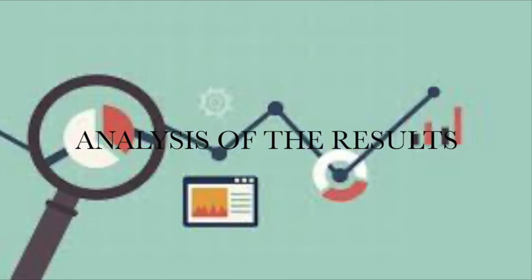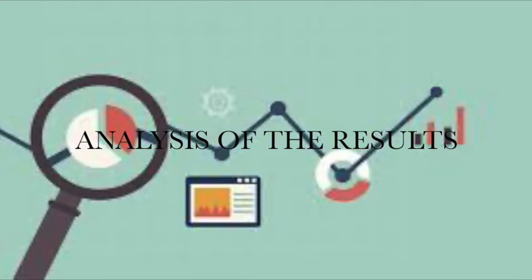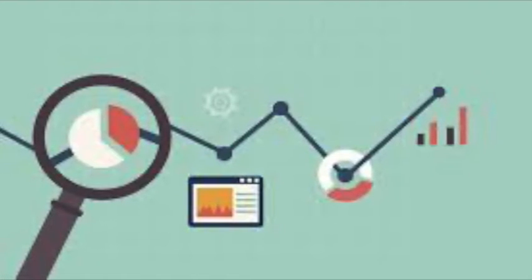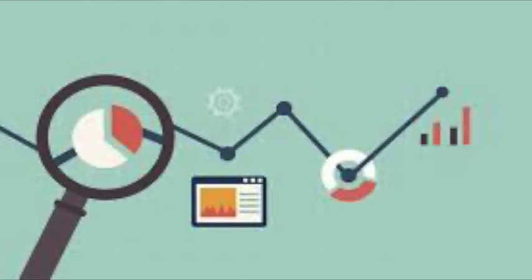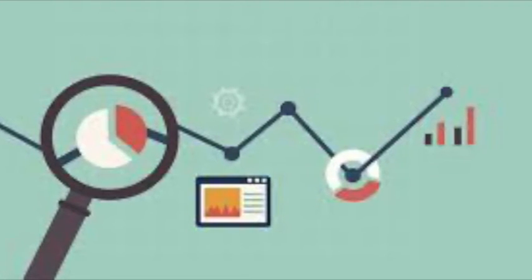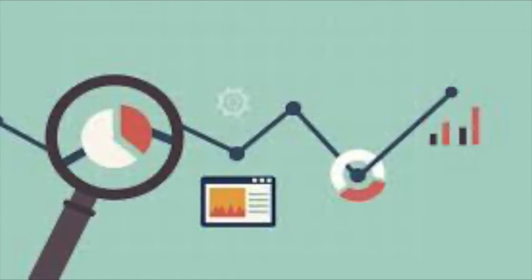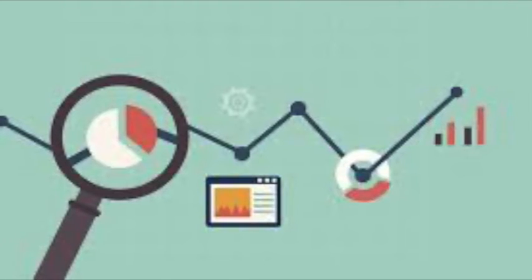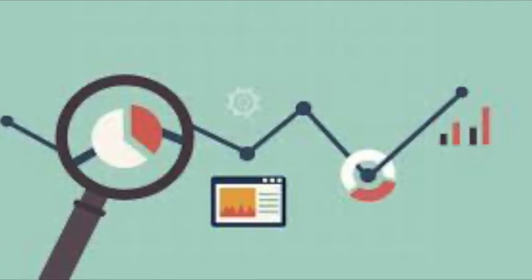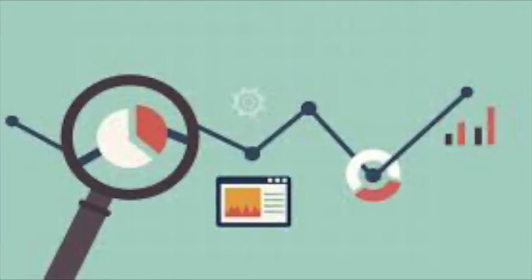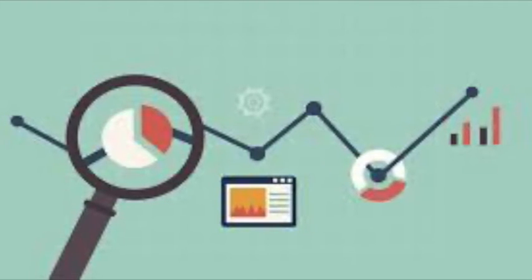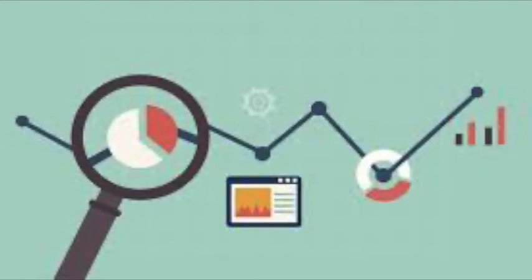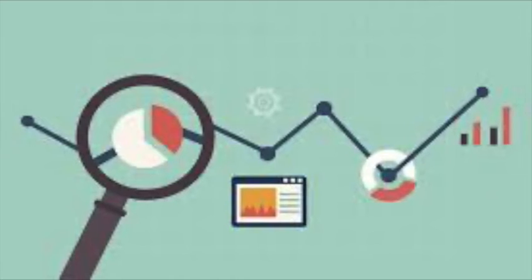Now we can see that there are 8 points that exceed the upper control limit and there are points that constantly touch the lower control limit. As they are defects, it's not relevant that they are on the edge of the lower limit, since this indicates good behavior, since there are no defects, and represents a good characteristic in terms of the quality that the press offers. Now, as for those that exceed the upper limit, it's necessary that the entire process be analyzed immediately to determine the causes that make these points drastically go out of control.